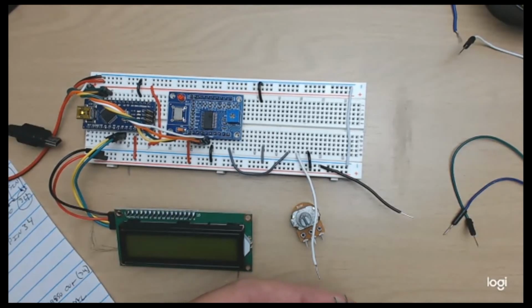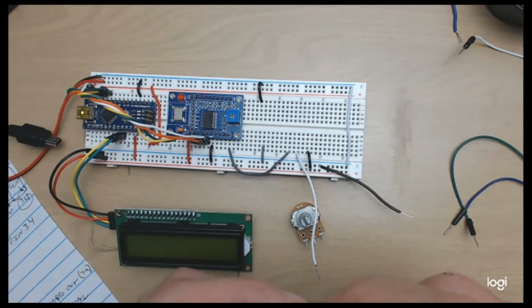And the A channel and the B channel and ground, or A channel and B channel, are how you determine left and right when you turn the encoder. And then on the other side are 2 pins, and those are just a switch. So when you push the button, those get connected together. And what will happen is one of those will go to ground, and one will go to a pin on the Arduino. And then when you push it, the Arduino will sense that the button's been pushed, and it can take whatever action you choose to take.